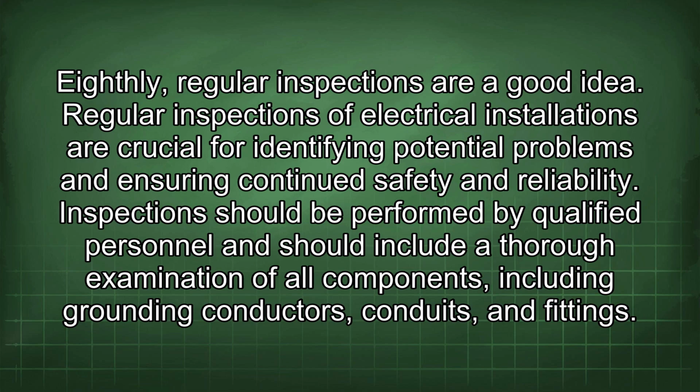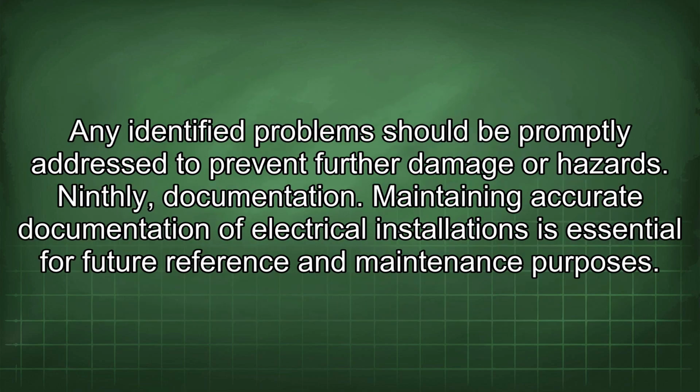Inspections should be performed by qualified personnel and should include a thorough examination of all components, including grounding conductors, conduits, and fittings. Any identified problems should be promptly addressed to prevent further damage or hazards.